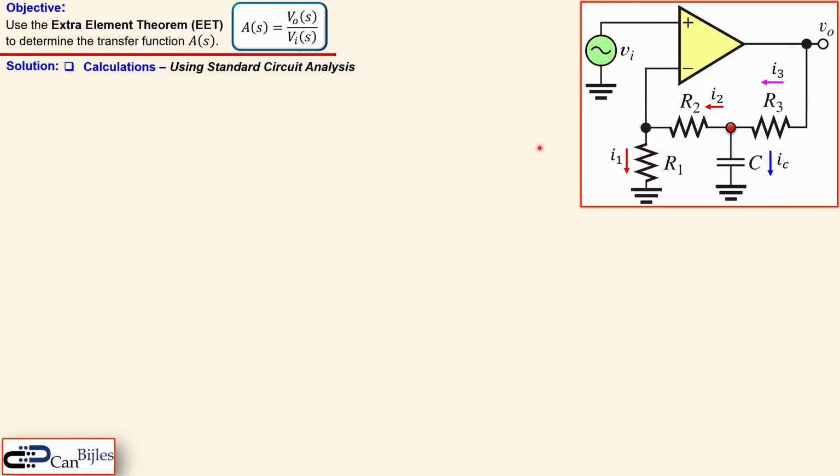This node here I will designate as X, and this node I will designate as Y. So I will use here now two nodes. I will use then Kirchhoff's current law. I will first do the Kirchhoff's current law at node X. That means I3 will split into IC and I2. So that's actually what I do here. And now I will use capital letters. They are not DC, but they are actually the frequency elements. So I3 is equal to I2 plus IC.